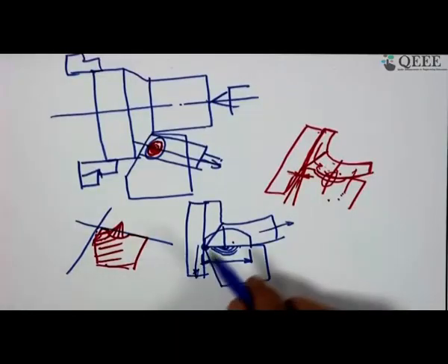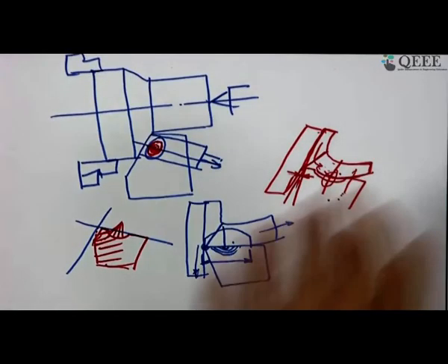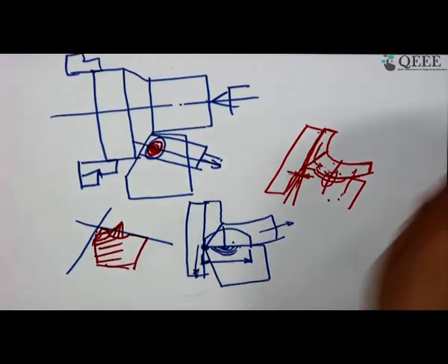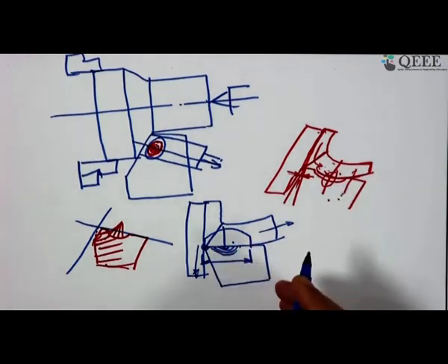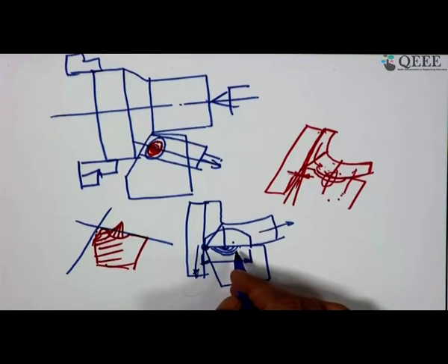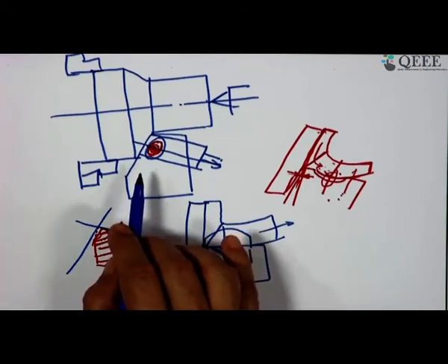One thing very interesting I must share with you: when we have this chemical reaction or dissolution, one layer gets removed. When it is a reaction layer or a dissolved layer, you have a reaction product, and that reaction product on the tool surface does not have the same property as the parent material.